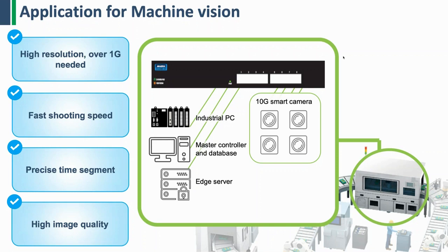We are not using any form of compression, simply because compression is never 100% accurate. We'll often introduce something called an artifact into the video, where the compression algorithm hasn't been able to handle the feed correctly. So if you're doing machine vision inspection, compressed video is something you have to avoid. You need the raw video for your video analytics system to be able to make decisions.